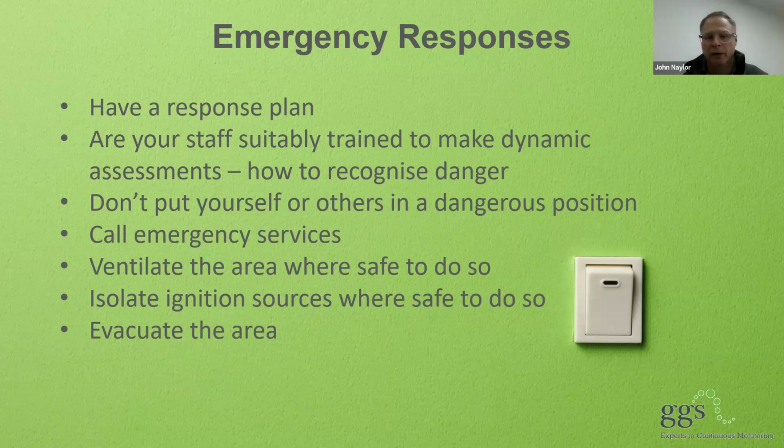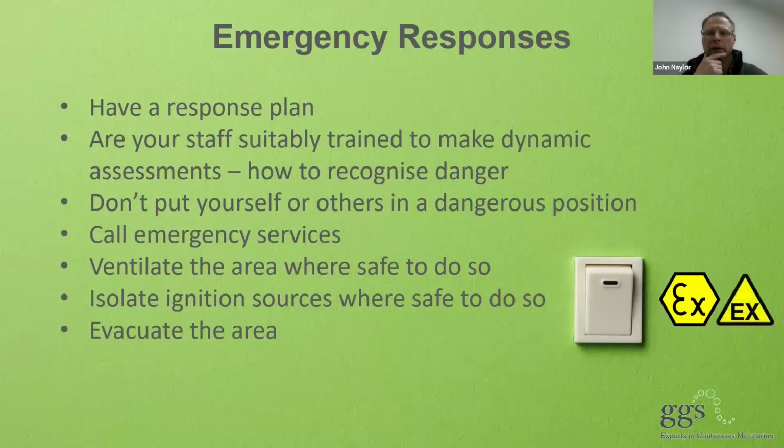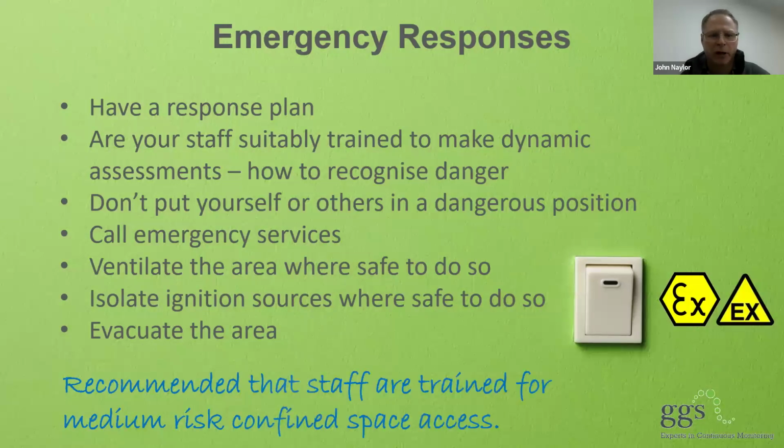Isolate ignition sources. So that's a light switch on there. There's enough energy in that to trigger a methane explosion if methane is indeed within the flammable gas limit around that point. So again, if you go monitoring with that suspect of hazardous gas, are you in there with intrinsically safe equipment? And evacuate that area. From our point of view, certainly from GGS, we recommend that you train your staff to medium risk confined space. That should give them enough knowledge in order for them to recognise the danger and know what to do.